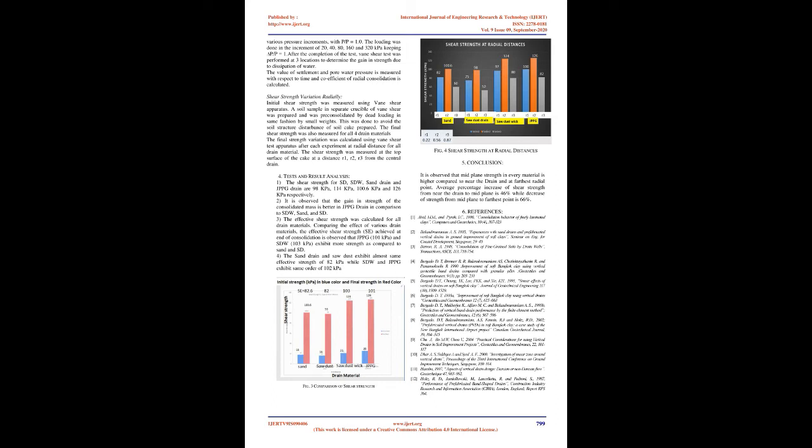Method of soil preparation. The soil used for this investigation was the clay mineral kaolinite, obtained commercially in the form of powder. To ensure full saturation of the sample, the clay was mixed to form a slurry with twice the liquid limit using distilled water. Density was sufficiently low to allow the removal of entrapped air when the sample in the consolidation cell was vibrated. The slurry was transferred into the oedometer after the cell body had been lightly coated with a thin layer of silicon grease to minimize side friction. The oedometer was then placed on a handle-operated vibrator and vibrated for approximately 1 hour, after which only occasional air bubbles could be seen on the surface.